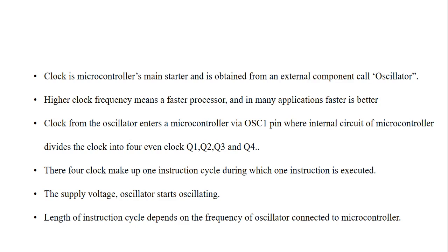All the peripherals don't come with individual clock signals. For example, in serial communication, we require the baud rate to be set. Serial communication is inbuilt with the microcontroller, but it requires a baud rate, and that baud rate calculation totally depends upon the crystal oscillator. So there is no need to take a separate clock frequency for baud rate generation.